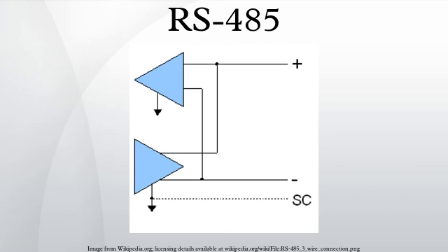The recommended arrangement of the wires is as a connected series of point-to-point nodes, that is, a line or bus, not a star, ring, or multiply connected network. Ideally, the two ends of the cable will have a termination resistor connected across the two wires. Without termination resistors, reflections of fast driver edges can cause multiple data edges that can cause data corruption.